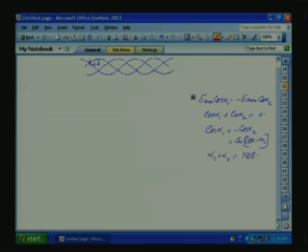So, to get the correct DC voltage for the two converters, if alpha 1 is fixed, alpha 2 will be 180 minus alpha 1. If we take care of this, for alpha 1 equal to 60 degree, alpha 2 will be 120 degree, then the DC voltage will be the same. So, let us draw that waveform now.